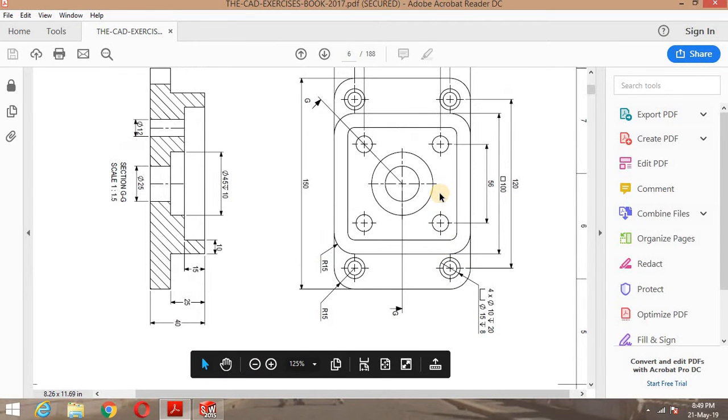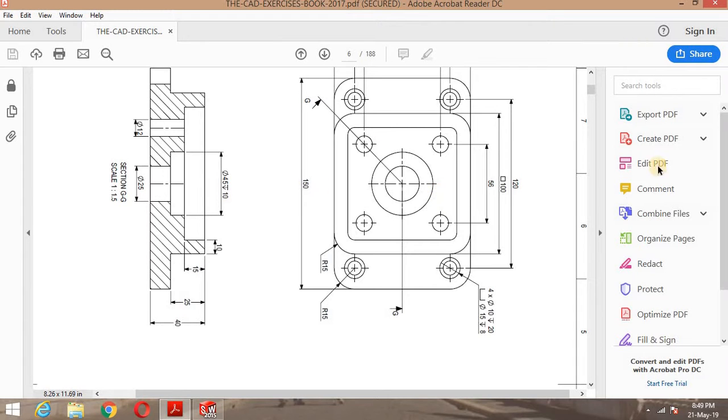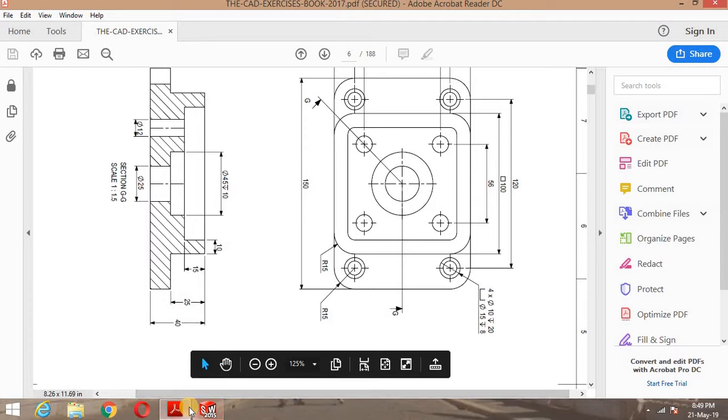Now what is the next step? The next step is very simple. We need to make the holes. For that I'll make one for the outer one and one for the inner one, and then I'll use the mirror command in features or the parts. So that will actually help us to make 2 more circles.